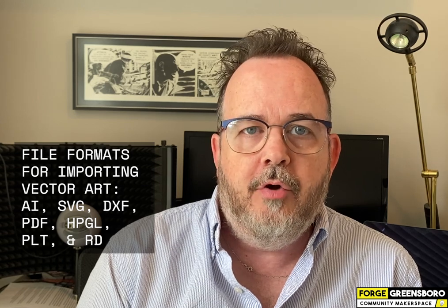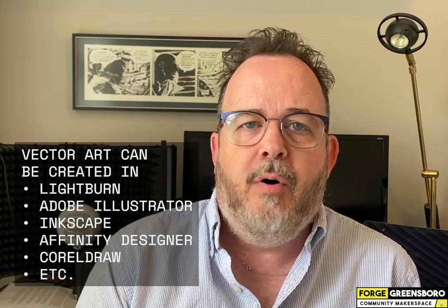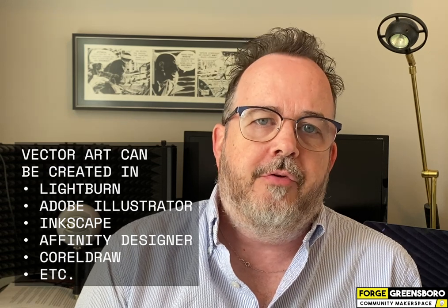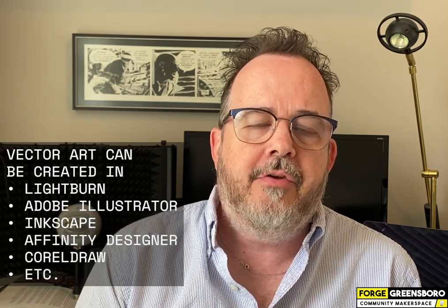We are going to be learning today about Lightburn software. The primary purpose of Lightburn is to convert graphics into laser instructions. However, it can do more than that. You can create your vector art in Lightburn. Vector art, if you've ever heard of file formats like SVG, DXF, .ai for Adobe Illustrator, those are all vector file formats. And vector art is art that is based on lines and points, basically. If you want to do any cutting with the laser, you are going to need vectors to do that with.